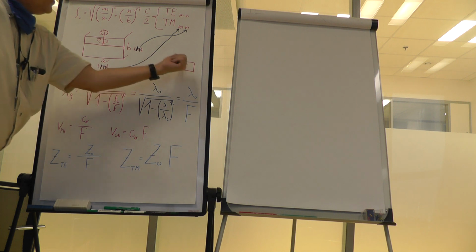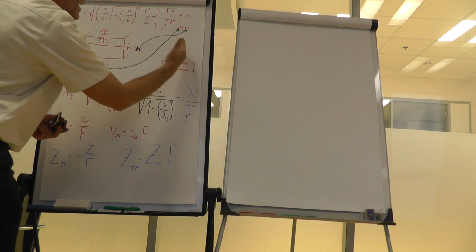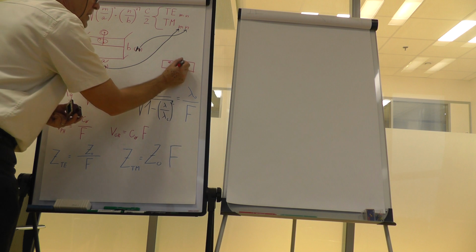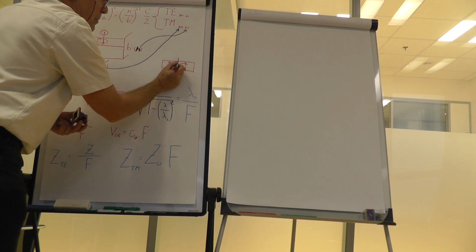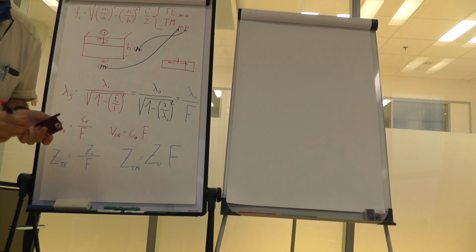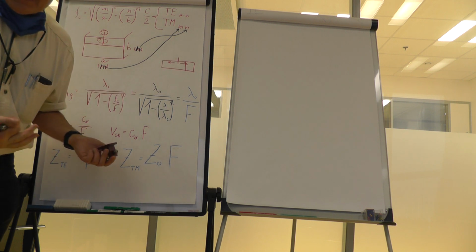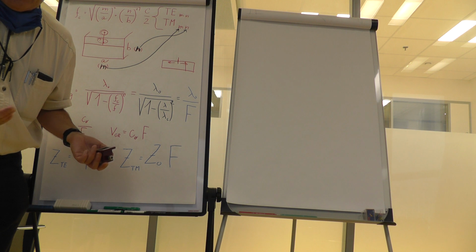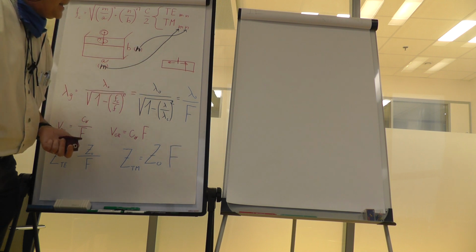Because mostly you need the wave to go one direction only, there is a short, let's say a quarter wavelength from that, so that anything that is transmitted in this direction is now reflected here and comes here in the same phase as the input signal. Remember, 90 degrees there, 90 degrees back makes 180 degrees, or 1 pi phase shift, which is antiphase. But by that time of propagation, the phase of the input signal has also changed in 180 degrees, or 1 pi. So this signal is in phase in the signal radiated in the other direction.